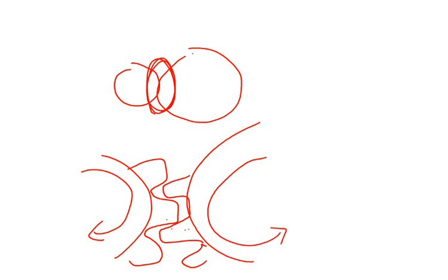So the whole idea is that at any moment, there's a single point of contact. There's always a little bit of a gap, so there's always just one point of contact between the teeth on the gears. And Newton's third law basically says if the tooth on the left gear pushes with some force on the tooth on the right gear, then the tooth on the right gear is going to push back with an equal and opposite force.